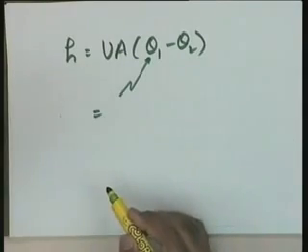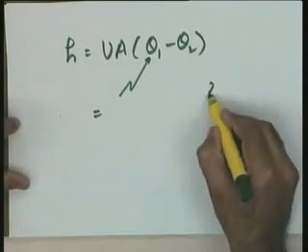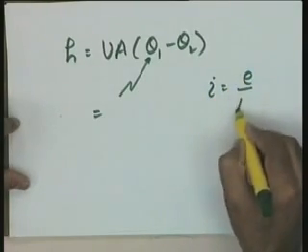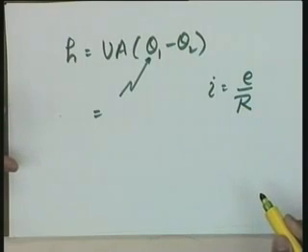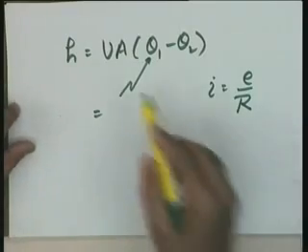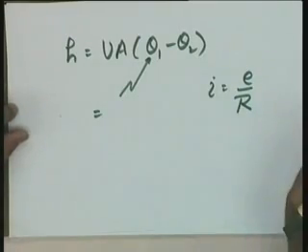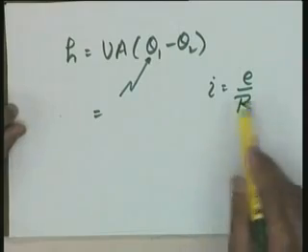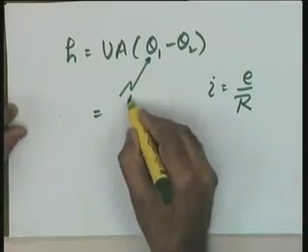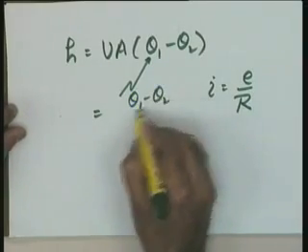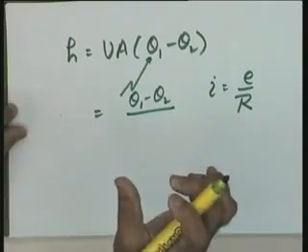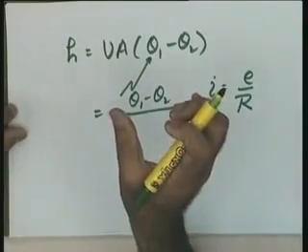Now, what I have done is that I have recognized this equation considering H identical to current. Please see, I equal to E by R is my basic equation in an electrical circuit. So, considering H analogous to current and temperatures analogous to voltage, I recognize a resistance parameter, and this I have written as theta 1 minus theta 2, the temperature difference, as the potential difference.